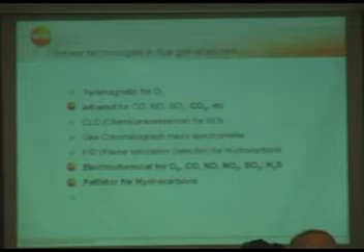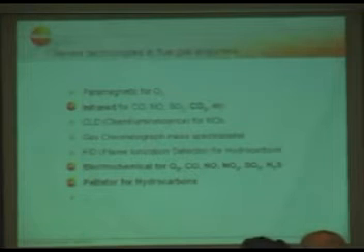This is also something we are using, Pellistor technology, but this is a kind of cheap way to measure hydrocarbons, and it has its limits because with the Pellistor you cannot measure hydrocarbons at a very low range. If you would like to measure below 1000 ppm, it doesn't make sense to use a Pellistor because the accuracy is plus minus 50% below 1000 ppm.